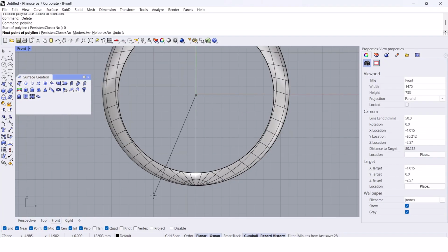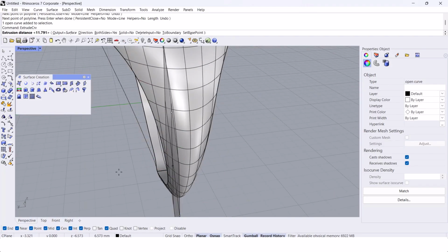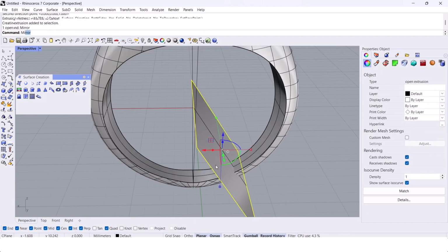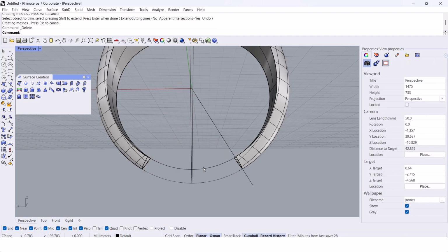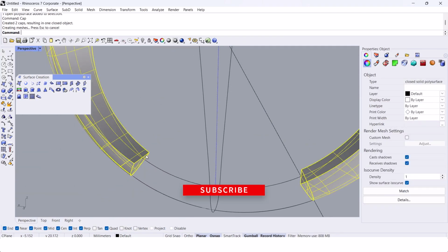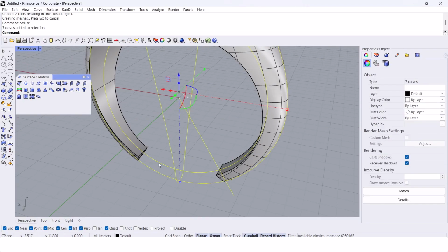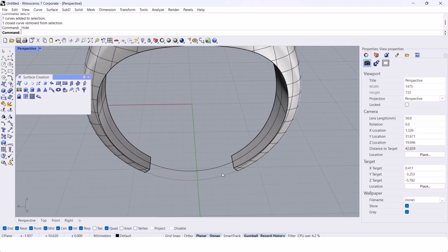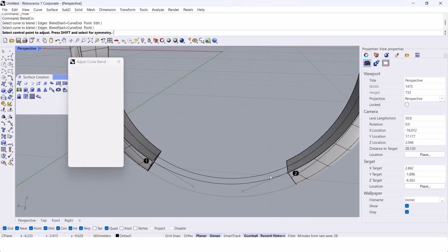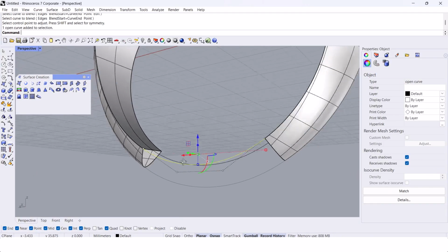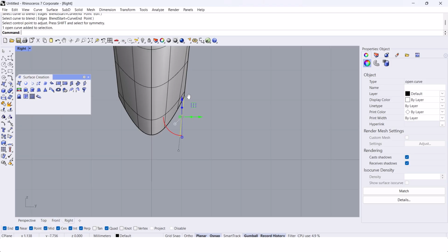Going to the front view, draw a curve, cut the shank, use the extrude, mirror, select this part, trim, split, or whatever. Tap, close it. Select all the curves, just keep the ring rail. You can remove the other curves or you can hide them. Then use the blend curve, connect these two parts together. Go to the side view, make sure it will be a smooth shape.